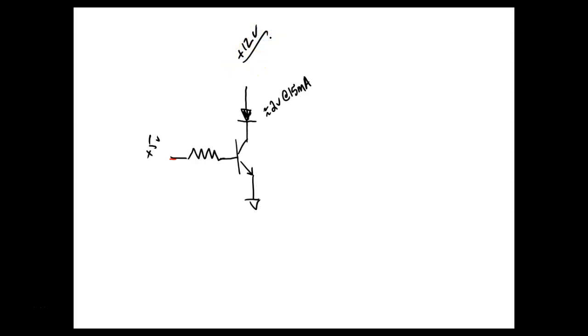This would be like saying, okay, on my car I have 12 volts, but I want 10 volts. Well, we could do it with a Zener diode, but this guy drops 12 volts. This one's going to drop approximately 0 volts, and this one's going to drop 2 volts. I'm going to put 12 volts up there. What do I need to add to the circuit? A resistor. Yes, we have to add a resistor to drop the difference between the applied voltage and the voltages in the circuit.